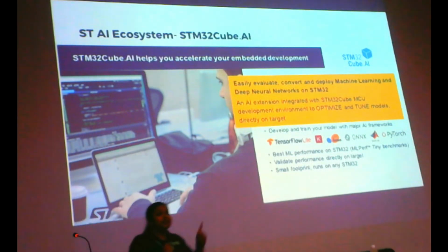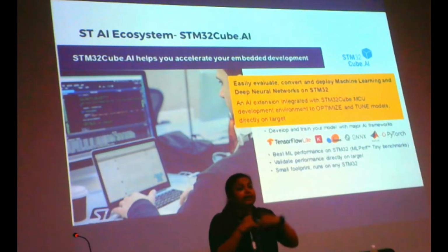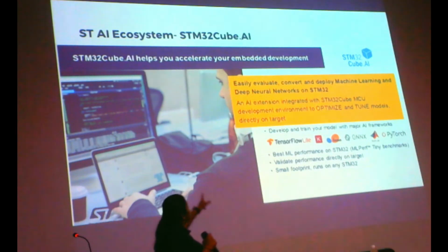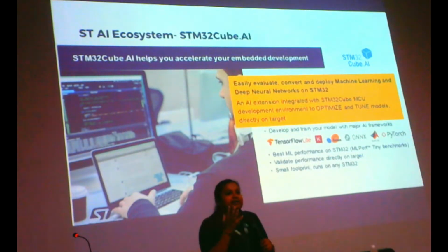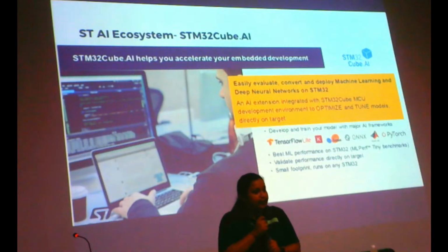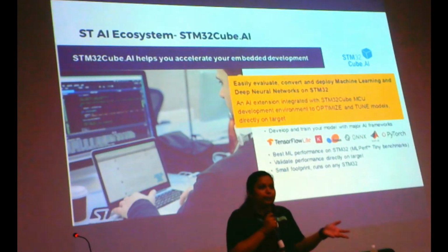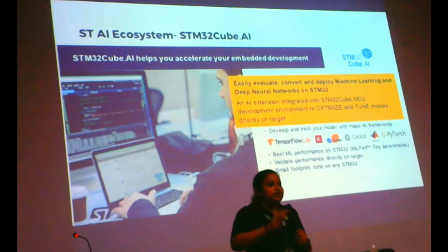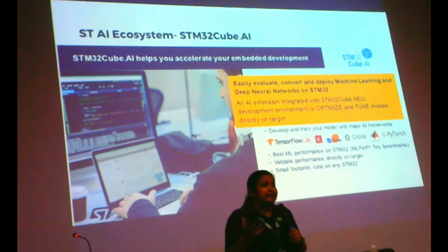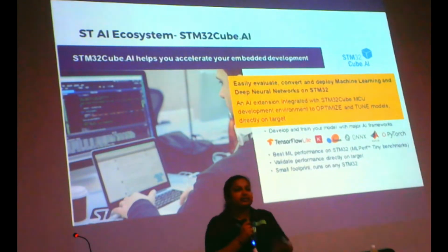So this was the first step. The NanoEdge AI software was the first step, where it builds the ML model for you. The second process is using the STM32Cube.AI software. It's a package basically. Most of the people must have worked on STM32CubeIDE. It's an open source platform for all the ST boards, based on an IDE platform like Arduino IDE. But the speciality is that you can configure the pins and generate the code, so you don't have to write the code fully. You can just write the print statements or some functions. In Arduino IDE, you have to write the code from scratch. That work is reduced in CubeIDE.